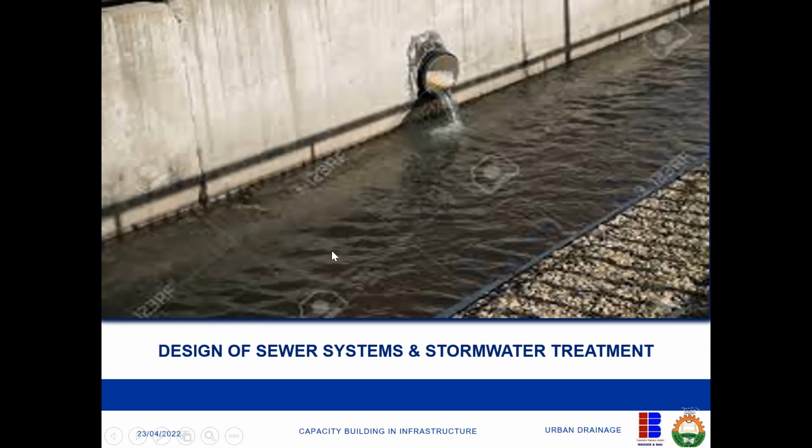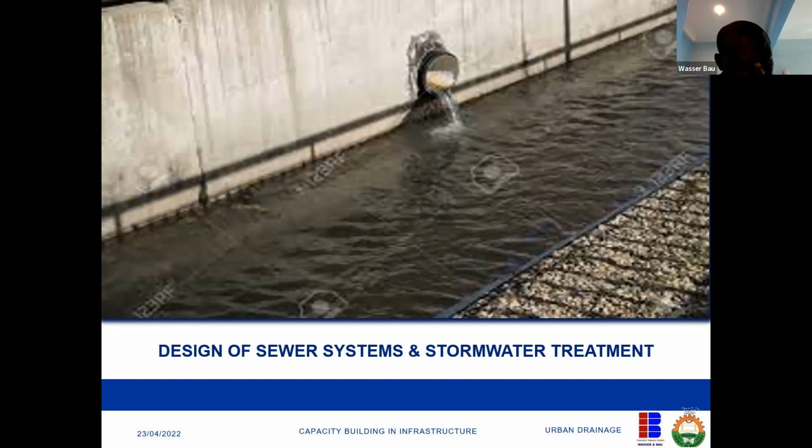Just to buttress that point, you mentioned the fact that mixing stormwater and sewer is wrong. In my years of working, I noticed, especially in a place like Guzape in Abuja, apologies to those who are not based in Abuja, that they have that issue. You get to a site, the plots are serviced, but you'll find only stormwater service manholes. So a lot of people are forced to pipe both sewer and stormwater into the same point.